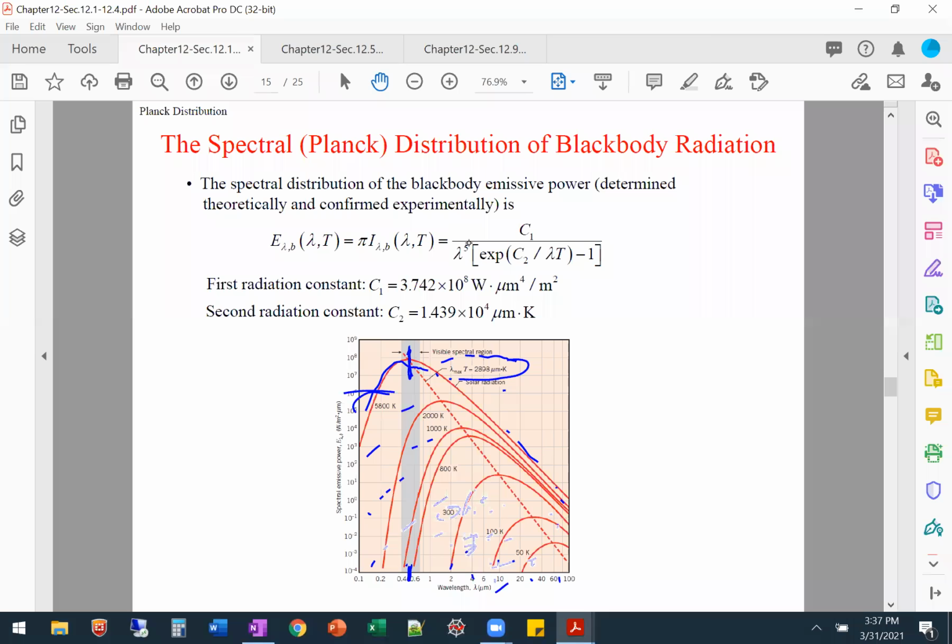If our pipe running through is at 300 or close to 300 Kelvin, it's going to be emitting above 2 microns in wavelength, right? So for the properties, you don't want to lose that emission back out to the atmosphere. So you don't want it to be able to transmit through the glass, okay? So you want that to be low.